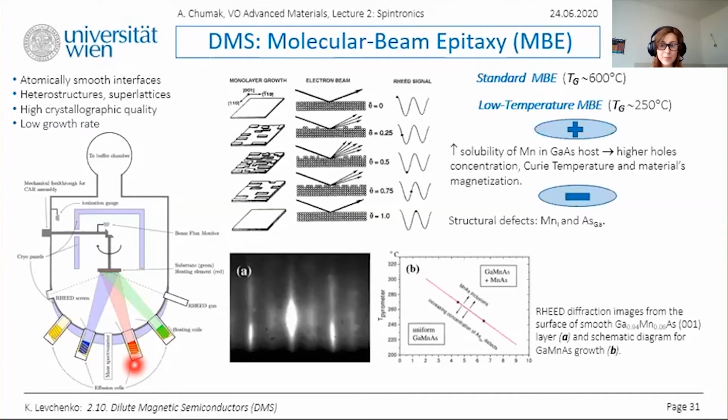The temperature of the source, which is very reproducible and stable, controls the flux generated from the effusion cells. This makes the generation of these fluxes of materials, in theory, relatively easy to control, to accurately get the composition of the alloy or compound in the end result.